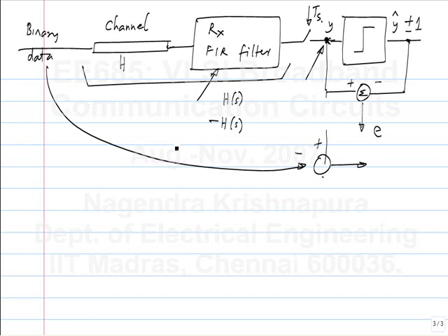So, what I am saying is, let's say you send all possible 7-bit patterns, and somehow you adjust the coefficients so that for this particular thing, which could be coming out of your 7-bit long PRBS generator, the error is 0. Let me also say that the ISI has less than 7 taps. Now, whether I use a 7-bit pattern or a longer pattern, the ISI will still be 0, isn't it?